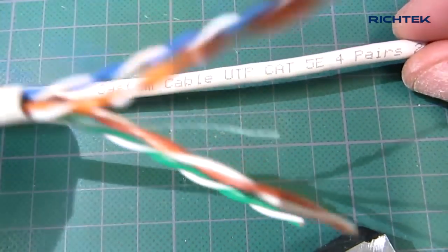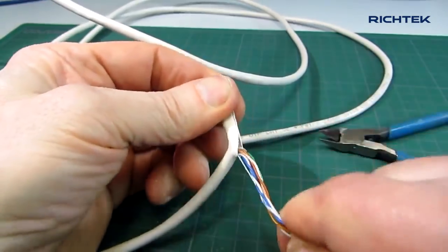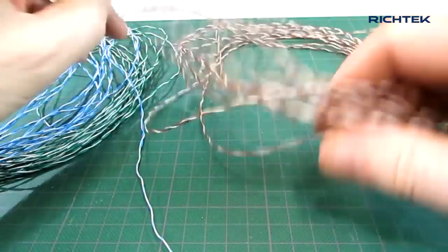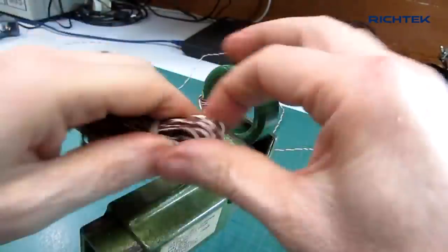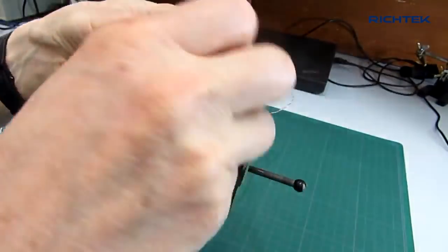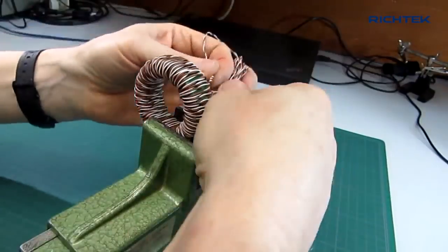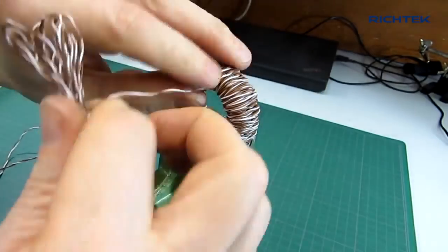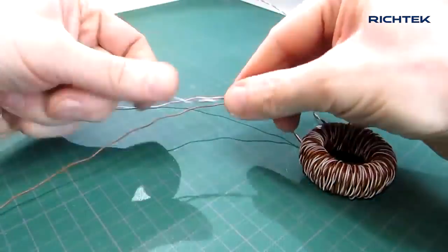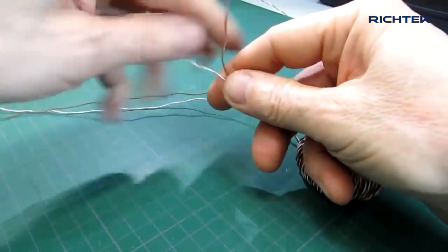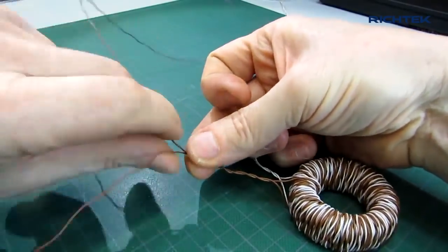For the windings, I used a twisted pair from a Cat5 Ethernet cable. For this transformer, I needed around 7.5 meters of wire. Start in the middle of the wire and start winding one end to fill the complete core. Place the windings tight. Then start the other wire end and wind the second layer, finishing close to the previously finished winding end. Now separate the twisted wire ends and then twist the wires with the same color to form the primary and secondary winding.